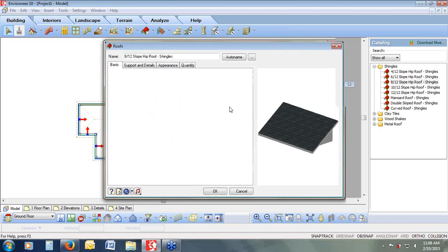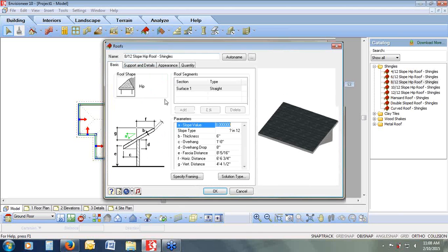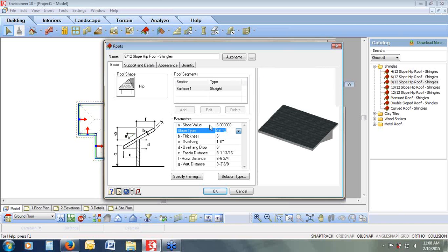By looking at their properties on those two sides that I selected, I can change the information about them. So I can say that instead of being an 8/12 hip, let's make these two sides simply a 6/12. And now that they are a 6/12, let's have an 18-inch overhang on them. So every side can be changed independently, so you can have multiple pitches, multiple plate heights happening, or just as I have done, selecting multiple sides at the same time as well.